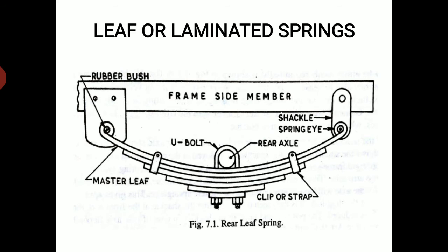The spring hanger is attached by a bolt. Rubber bushings are used to provide insulation for the bolt from the spring hanger. The rubber bushings serve two purposes here. They absorb vibration and thus prevent it from getting up to the vehicle's frame.